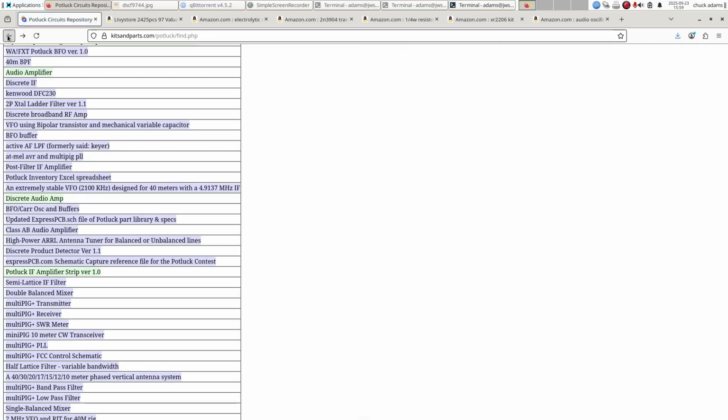Also, won't do it here, but I want you to go on the internet and look for the Solder Smoke DC direct conversion receiver project, and there's a discrete transistor audio amp there, but it requires an audio transformer, and you've got a better than 60% chance that you will not get it to work. Because one, it's hot, and number two, it just needs some tweaking. Been there, done that.